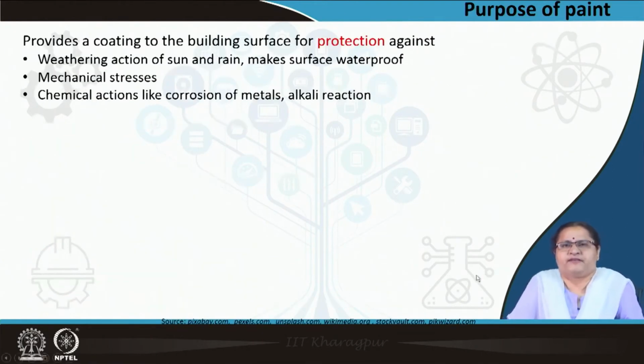So what is the purpose of putting the paint? As I told you, one was hiding the surface imperfection. But what are the other major purposes? It provides a coating to the building surface for protection against weathering action. Who are the enemies? Sun, the ultraviolet rays, the rain.